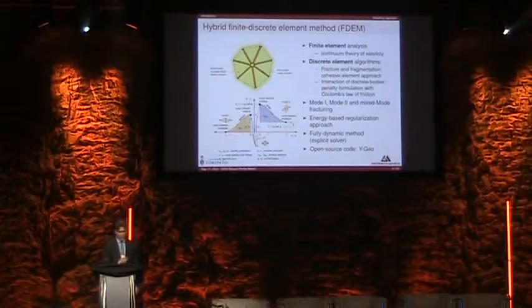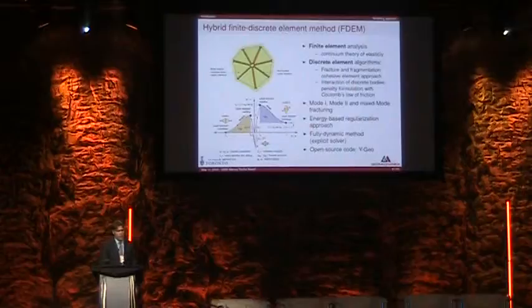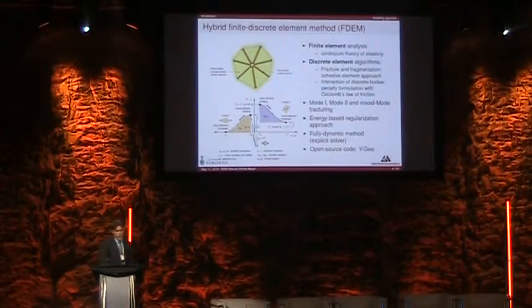Just very briefly, this method works as a hybrid continuum-discontinuum approach, where the finite element analysis takes care of the elastic deformation of the rock, and this is coupled with discrete element algorithms to capture fracture and fragmentation using a cohesive element method, and also the interaction of discrete bodies, either if you have pre-existing discontinuities or discontinuities that emerge during the fracturing process.